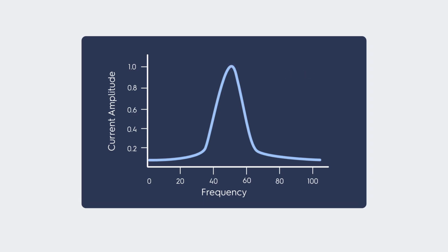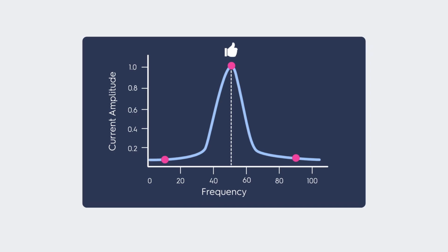At a very low frequency, the current is small. At a very high frequency, the current is also small. But for a fixed input voltage, the impedance is smallest at resonance, so the current reaches a maximum. So the graph tells a simple story. The circuit likes one frequency most, and it responds less and less as you move away from that frequency.